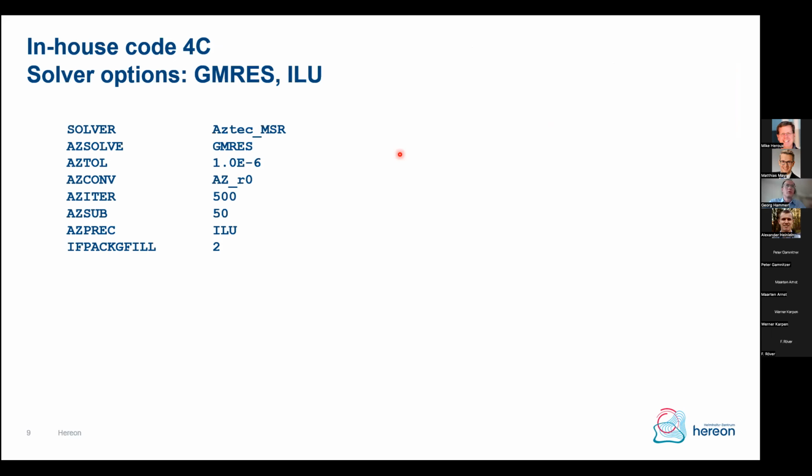In another part of the documentation of Abaqus, I found ILU in use. So the AztecOO package with GMRES as Krylov method, and the ILU preconditioning with a fill limit of 2. Iterations and tolerance are set to the same limits as Abaqus usually does.